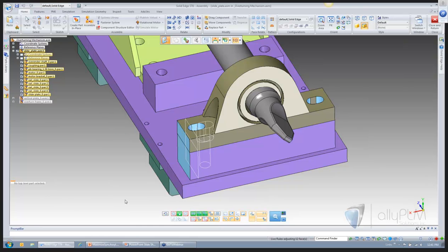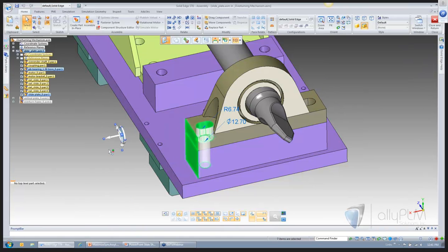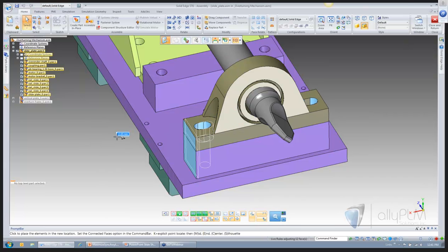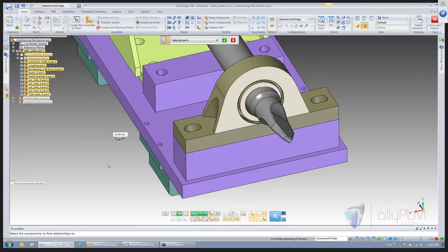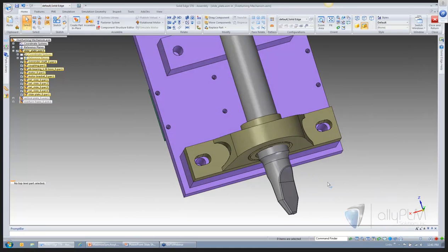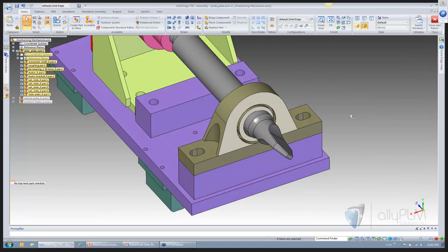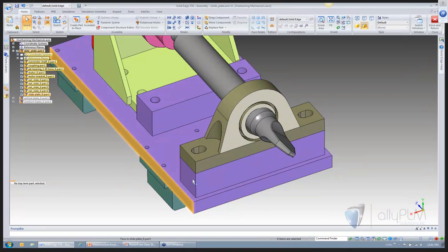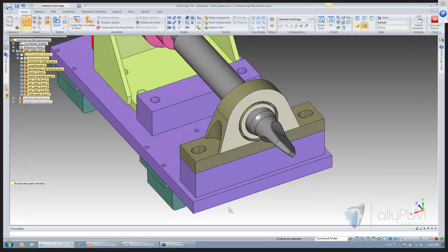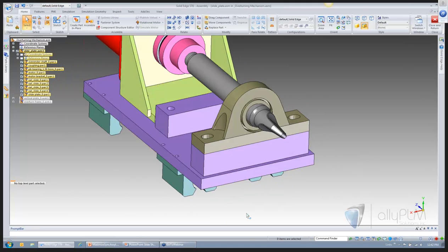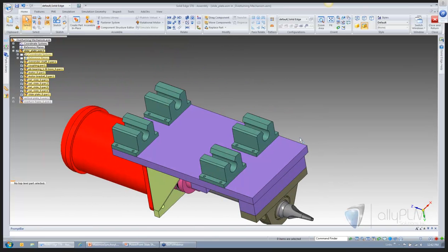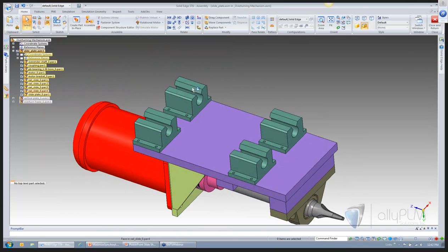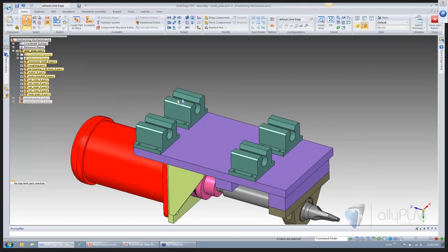So being mindful that the steering wheel is kind of placed out here in space, I'm really just making a delta move. I'm going to move this by 15 millimeters, and by default that gives me 30 on my overall width, which was the design change that we really wanted to make. So instead of having to go to two parts individually and change multiple features, I'd have had to change the block width and the slot location. I'd have had to change the block width and the hole location. We can make all those changes in the synchronous assembly, and it actually allows us to honor design intent a lot quicker and a lot more robustly and accurately.